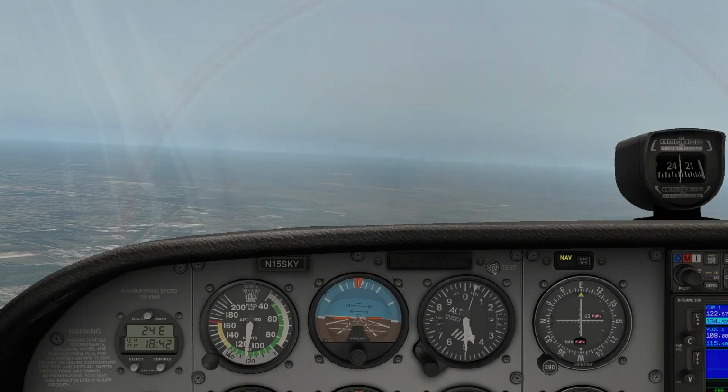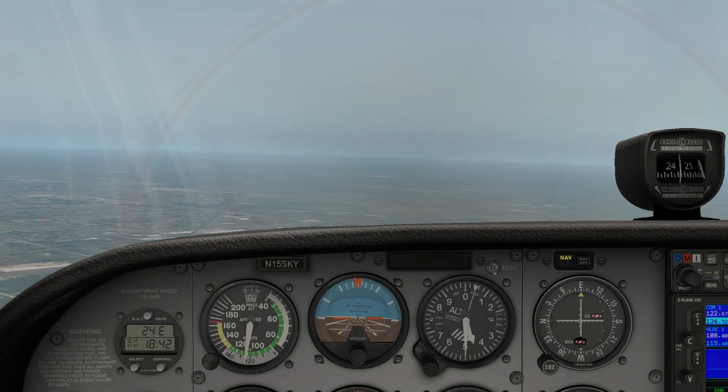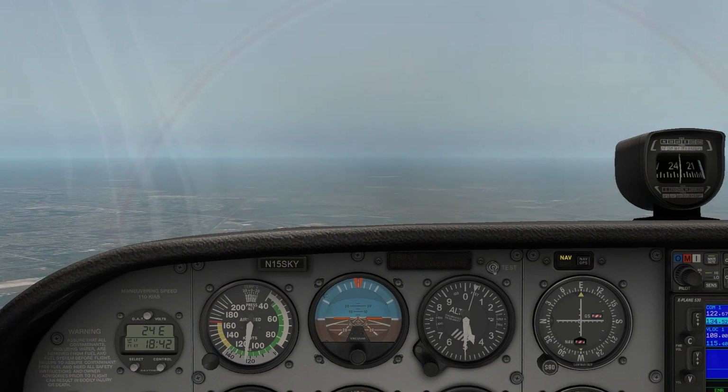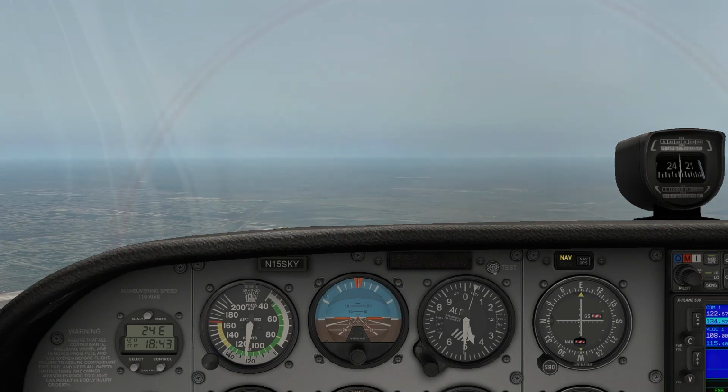Since you cannot feel this roll, you need to be aware of your airplane's attitude and make the frequent but slight adjustment to remain level. It literally is a slight tipping of the wing to the right. This is a very important lesson, and you will need to practice this throughout your entire training so that it will become second nature. Eventually, you won't even think about doing it.